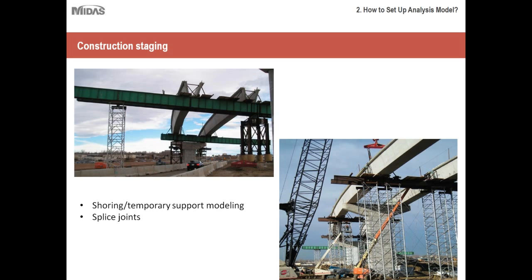Then let's move on to the fourth challenge, which is the construction staging itself. As you can see, all these bridges are heavily supported on their shoring, and depending upon the road alignment underneath it, you can either have just nice support right under the bridge, or you can opt for bent caps and then provide shoring.